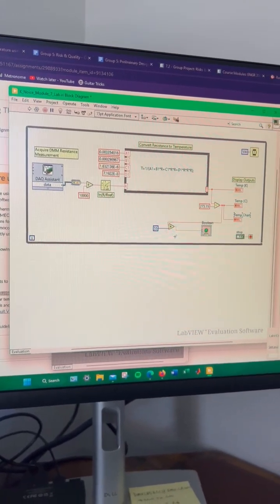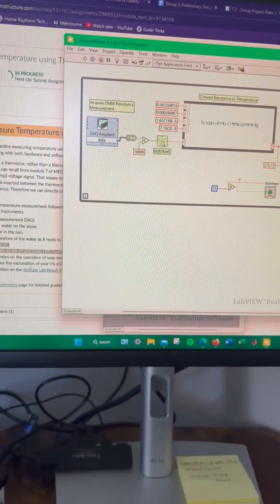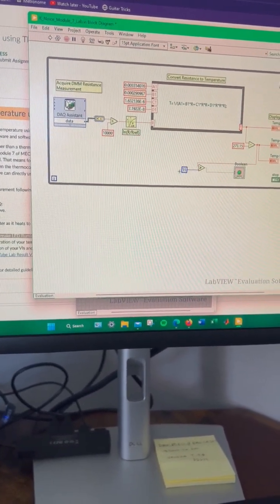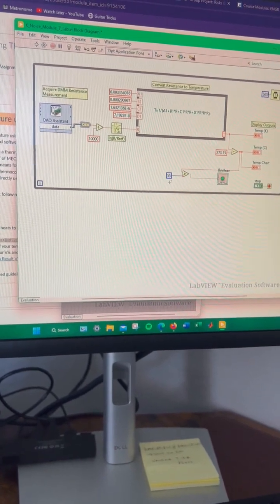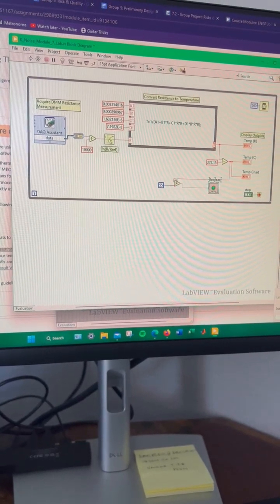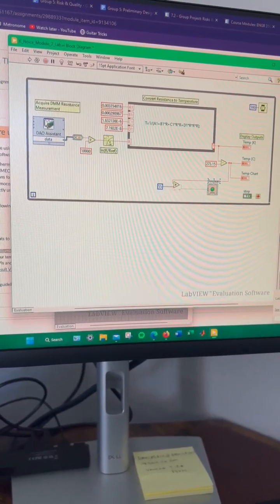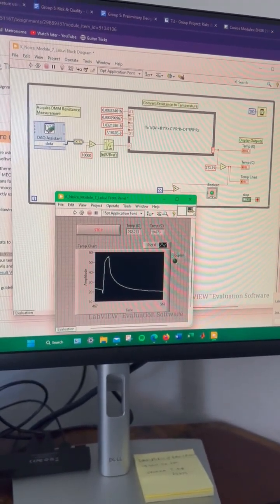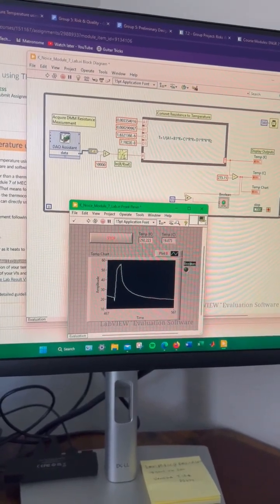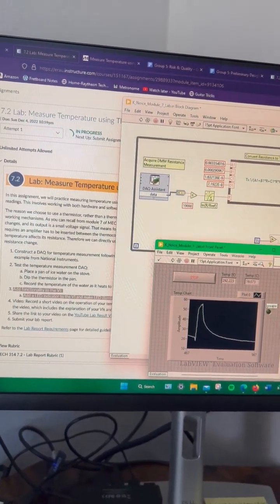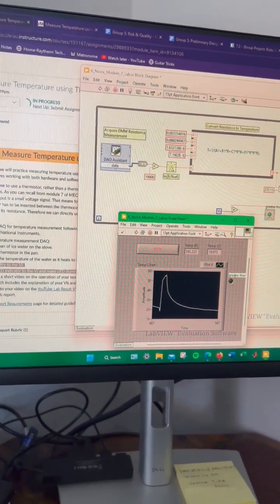And then we have, I can't move my computer, so I have to bring water in here. So I set the green light indicator to 55 because I won't be able to boil it to 70. So it'll indicate green when it gets to 55 degrees Celsius, and I just extended that value to be greater than 55, and then that will indicate our green LED here. We can change that to greater than 55.